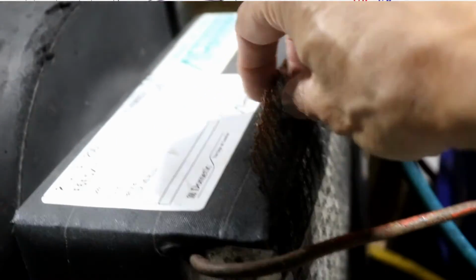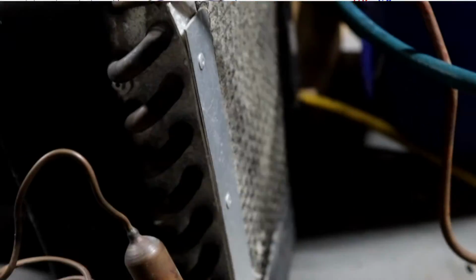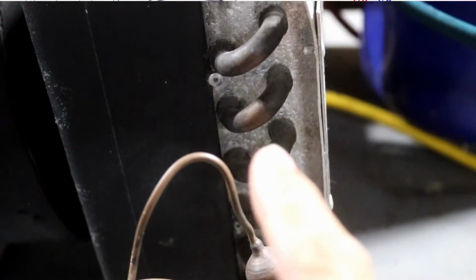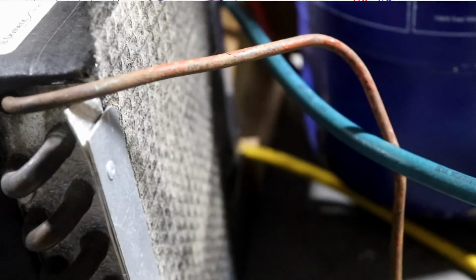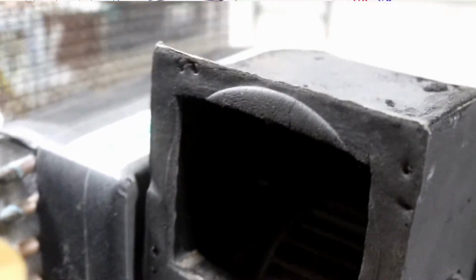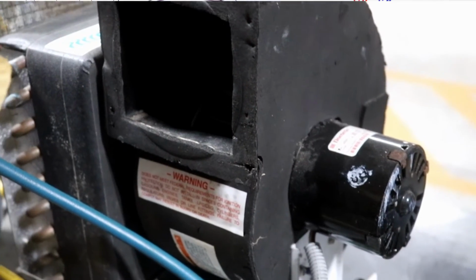Why? Because this element, the blower, sucks the ambient air of the room, and the air passes over there. Here is the filter that you replace periodically. The air passes over there. Remember that those pipes are practically frozen. When the air passes over there, because the fan is working, you have cold air coming out, because the fan is spinning at high speed, and you receive cold air at the output of the blower.